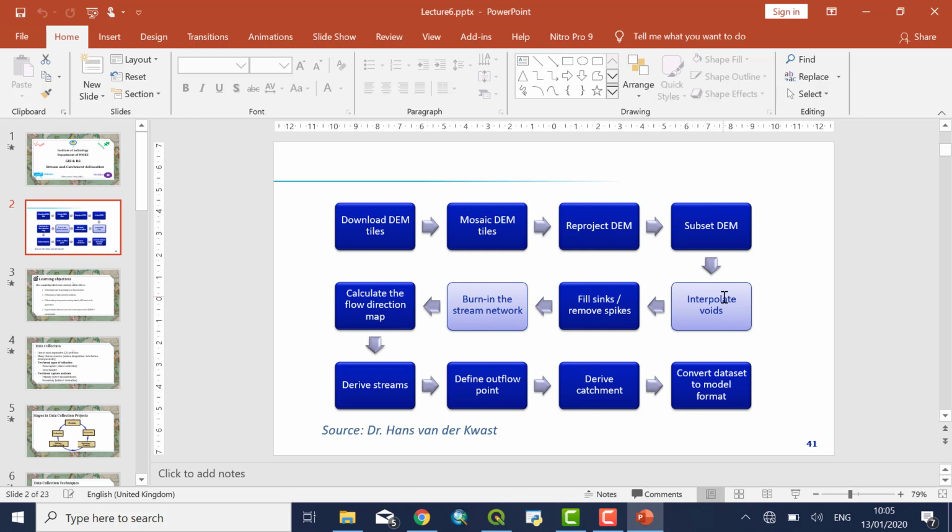In this case, we are using the QGIS desktop application. Then, if the landscape contains real sinks, for example lakes or reservoirs or other depressions, these need to be added back after removing the pits.